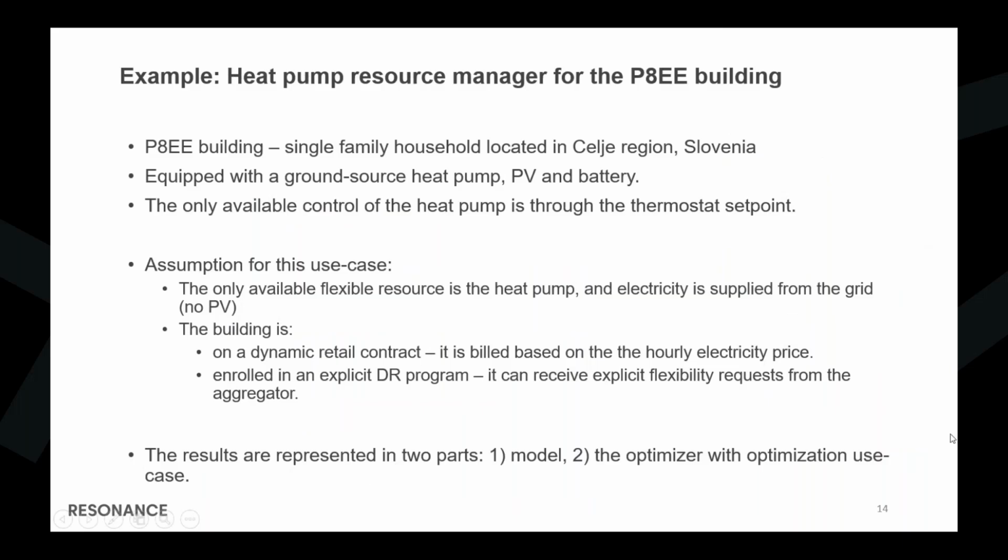Now I will present one specific worked example of the heat pump resource manager for a P8 building from the Slovenian pilot. The P8 building is a single-family household located in the Celje region of Slovenia. It's equipped with a ground source heat pump, PV, and a battery. The only available control of the heat pump is through the thermostat set point, right?